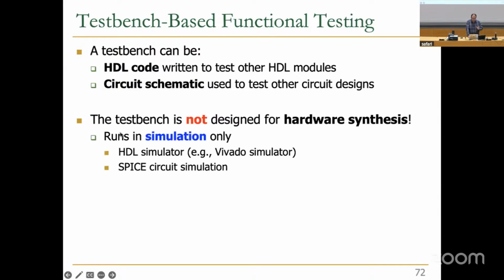So it only runs in simulation, and there are many commands in your test bench that are not synthesizable, like definitions of timing, some delays that we're going to use in order to generate some pulse, or maybe some functions like print display. These are not synthesizable, right? But you are using them in your test bench in order to test your system for simulation.